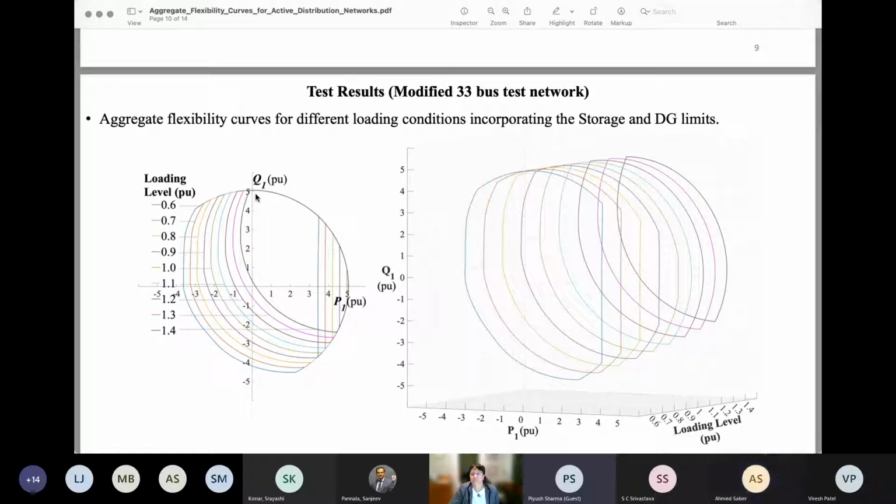Of course, I have to do my own optimization exercise, or essentially I have to disaggregate again. Let us say I get 2 plus 3j that the TSO in the higher level of hierarchy shares. You can draw this much amount of power. This is optimal according to him. Now I need to disintegrate the 2 plus 3j among all the distribution networks on my own. So I have to do my own optimization exercise, but I do not have to share that exercise with the operator in the higher level of hierarchy or any of that information. That is the only advantage.